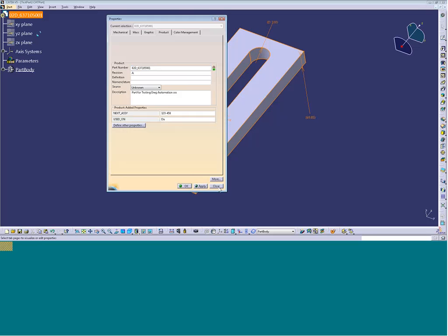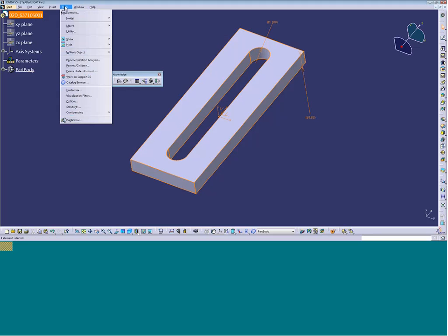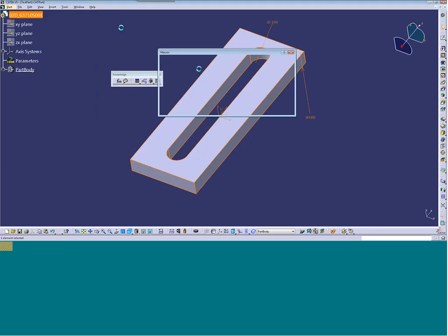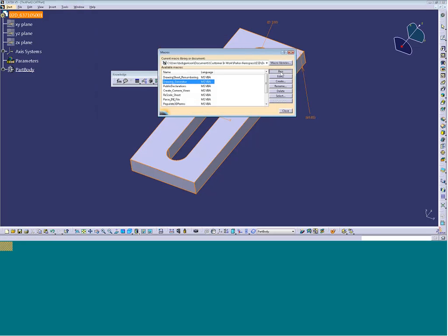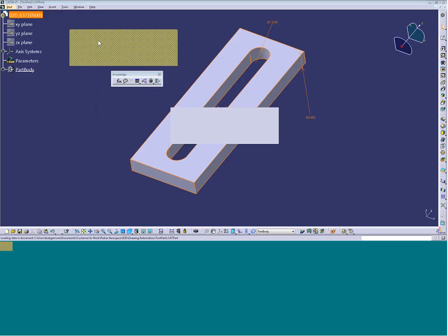So one thing that I need to do in here is concern myself that those parameters were missing. But if I come in and run my drawing generation macro, we'll run that drawing generator, and it tells me there are some parameters that are missing from this part. So I need to correct that before I can proceed. So this pretty much blocks the user from generating.